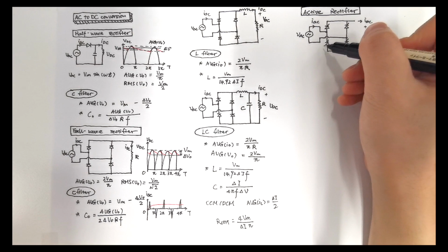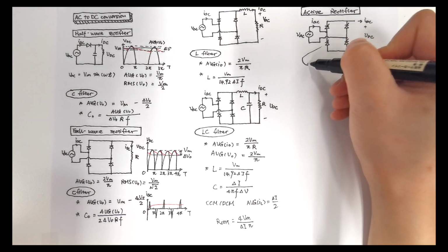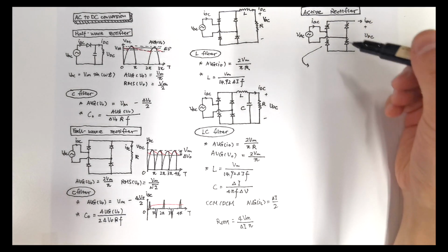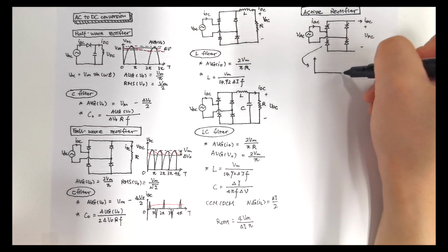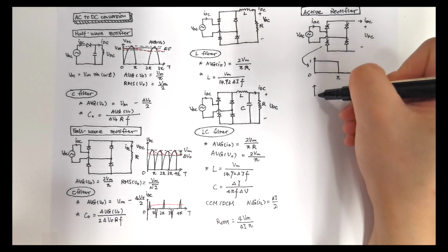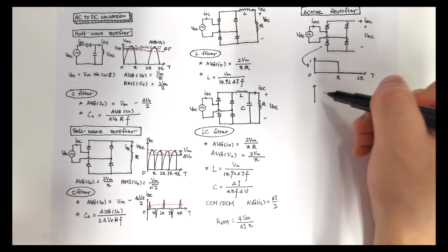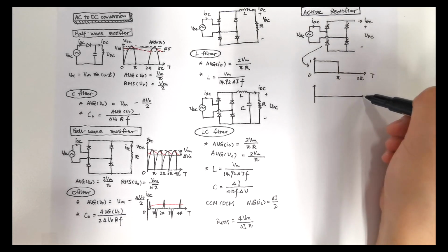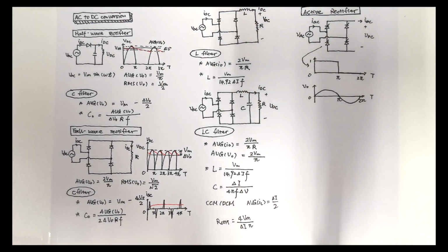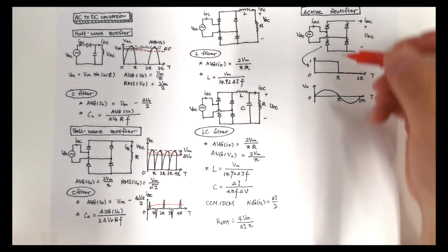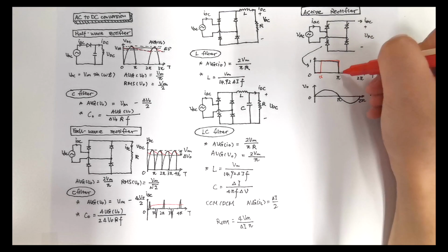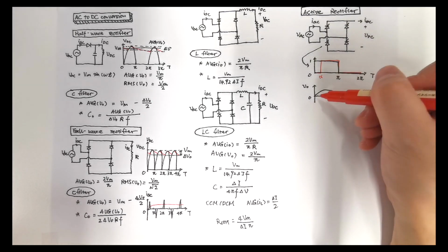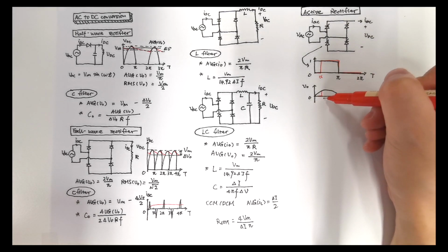If we look at one thyristor in here, if it is a diode, our turn-on pattern looks like this, and our output voltage looks like this. But with thyristors, we can delay a phase of alpha like this. So the output voltage will become like this.